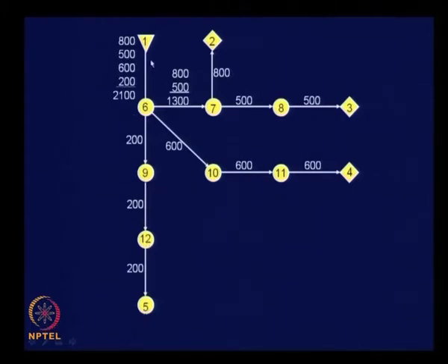Now sum up the assigned units of traffic volume for each of the links. We have 4 components for 16 totaling 2100 PCU per hour, and there are 2 components for 67 amounting to 1300. All other links have only 1 component. Now the picture with regard to link volumes is very clear to us.